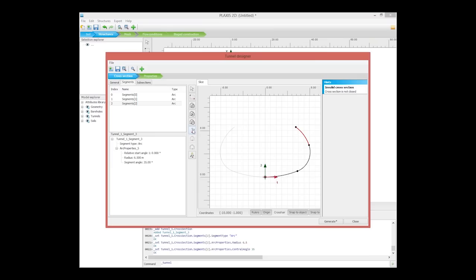The extend to symmetry axis will generate an arc with the following properties. The arc will start at the last created point up to the symmetry axis, and it will also ensure continuity of the tangent at this point and a tangent equal to 0 at that point along the symmetry.